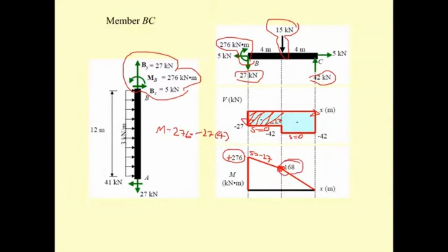Okay, just move this one, and then the shear is minus 42 now, so the S here is going to be minus 42. But point C is the pin. The moment here is 0, so no need to compute, just drag the line here, and you get the moment diagram for the beam BC. That's not hard, right? It's pretty easy.